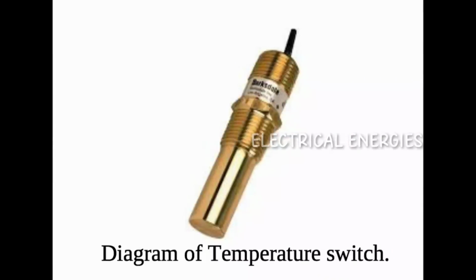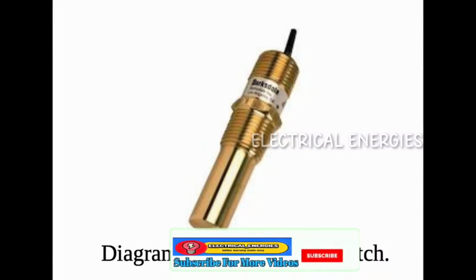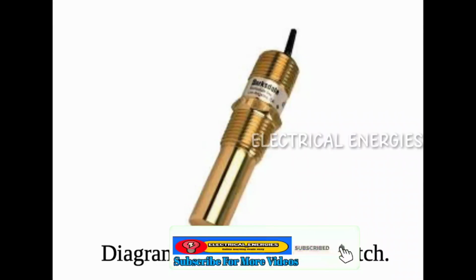Some of the more advanced switches, though still relatively simplistic in all honesty, employ a brass bulb filled with gas or liquid, with a small tube linking this bulb to a pressure-sensing switch. When the bulb is heated, the liquid within the bulb expands. The expansion generates a pressure increase, which actuates the mechanism of the switch.